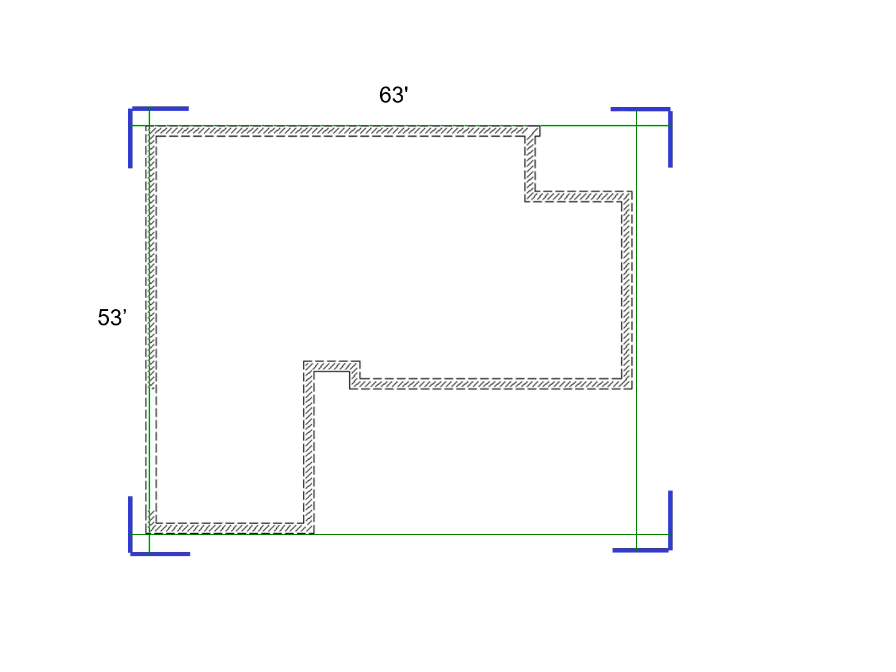And I said, okay, what I'm going to do is set up some batter boards, 3'6" outside the four corners of the building. That's just where I chose to put them up. If it was a holiday and I'd been drinking the night before, I may put them 6'6" outside the four corners. I don't care. It's where the strings intersect that I care about. I'm going to have those strings intersect on the outer face of the footings. Or no, outer face of the wall. Jeez, I told you, I was drinking last night, I guess.